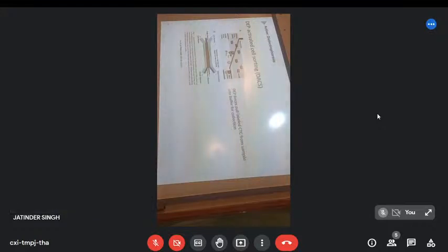Some of them don't. So some of them will find their way into the acceptor channel here with the buffer flow. Some of them won't. They leave the chip for different outlets, and that becomes the source of our separation. So by doing dielectrophoresis here, we can push some particles into the acceptor flow and not others.